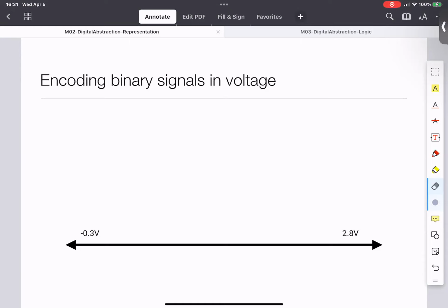If any of you have done a device course, this is the so-called threshold voltage of a transistor. It tends to be around 0.6 or 0.7 volts nowadays, and you need about twice that. So that's where 1.2 volt things come from. Your Arduinos are usually 3 volt, 3.3 volt, maybe 5 volt. Those are the kinds of voltages.